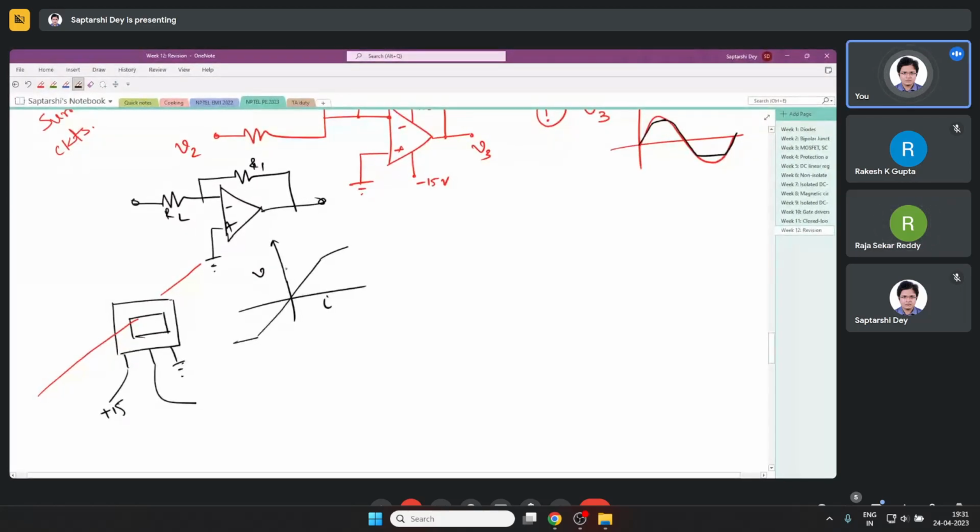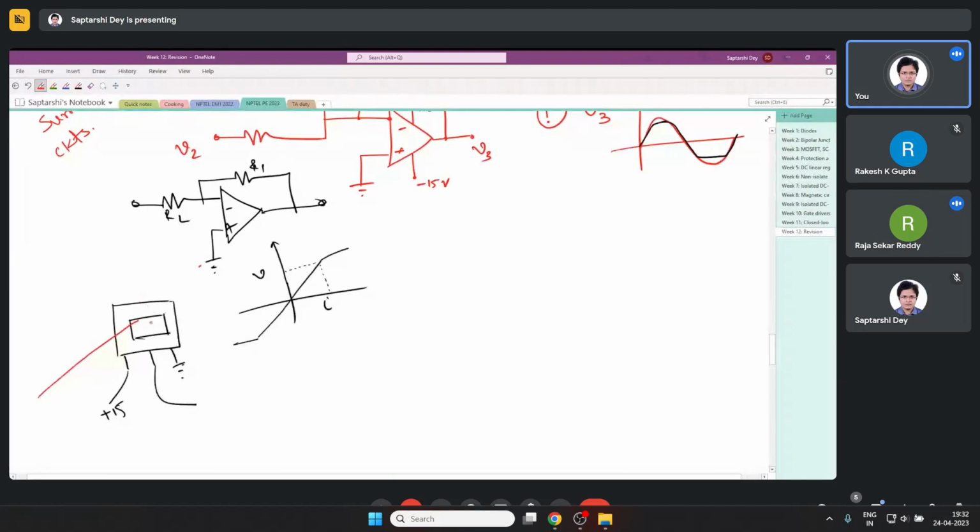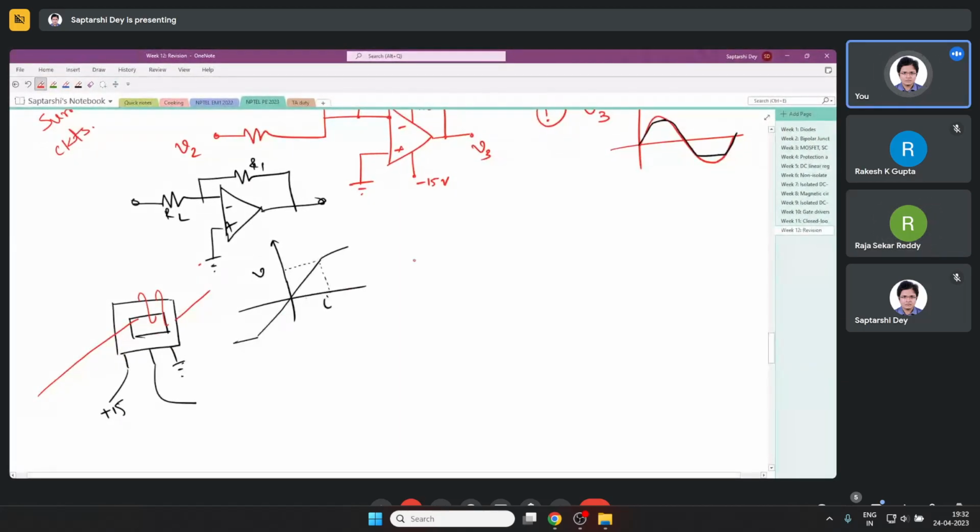That is, when my motor is operating at full load, the sensor should be giving very close to its full voltage. I want this for its sensitivity, or somewhere in the sensitive region. For this, I will maybe give several turns, depending on how much current is going and how much is here.